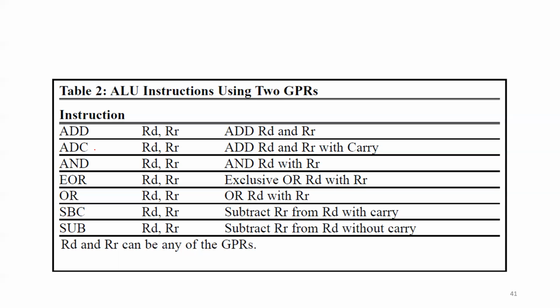In this case, the result would for sure be wrong, because you don't have enough memory space to hold data greater than 8 bits in a size of 8 bits. So what happens is the memory location of 8 bits will be filled with data, and the remainder will not have any place to be stored. In this case, one of the registers we have in our processor, which we are going to discuss in the next class, is called the status register or flag register. It will have one bit called carry.